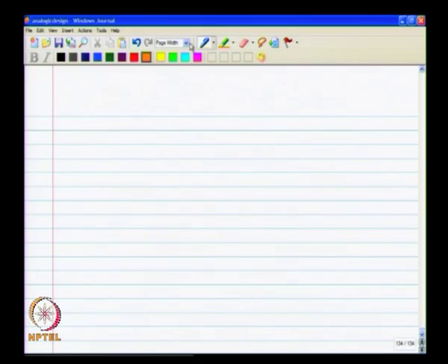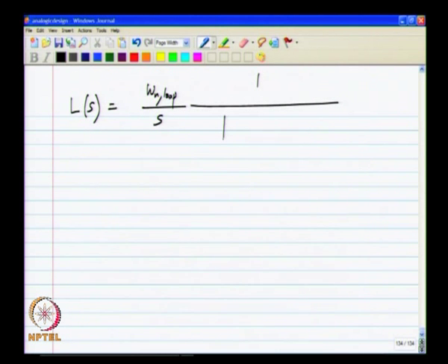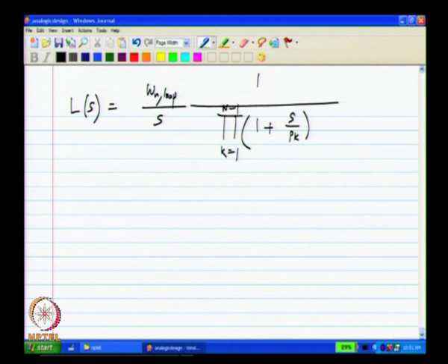So, as I said, for higher order systems, the same phase margin is used because when you have a large number of poles beyond the unity loop gain frequency, you can think of each of them as contributing to a certain amount of delay, and the total delay has to be limited to a certain value. Okay. So, to conclude, in general the loop gain will be of the form omega u loop by S and a number of extra poles which may not be at the same frequency. Okay. I have taken n minus 1 extra poles, this gives you an nth order system.